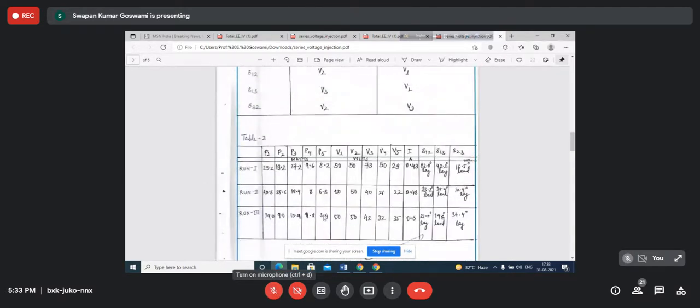So this was done, and then in the third run, P5, though it is of very small magnitude because it was very difficult to bring about this situation, P5 was made greater than P4. Had we made that arrangement, then you could actually vary this power through a wider range. Now, since all the sources are from the same point, bringing about that difference becomes very difficult in this environment. That is the main negative point of this experiment done in the laboratory. That's why you see that P4 is only 3.4 watt, and P5 is now 1.8.